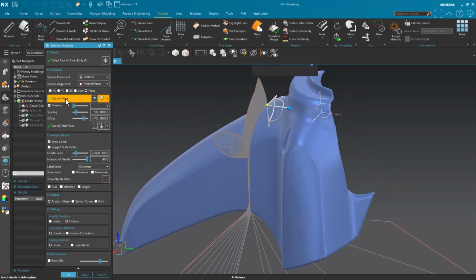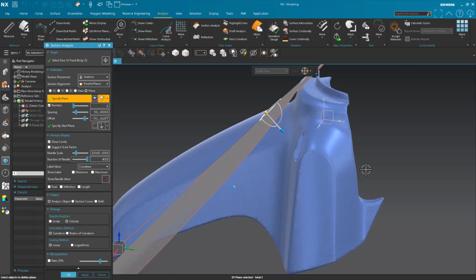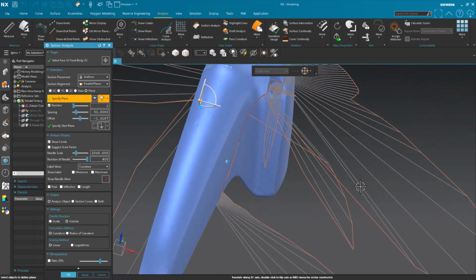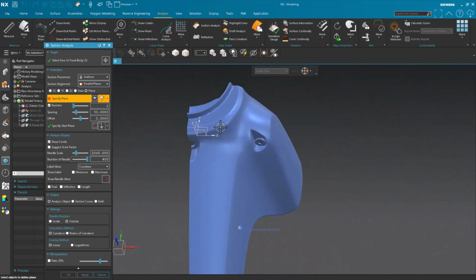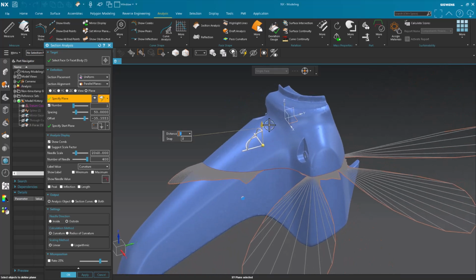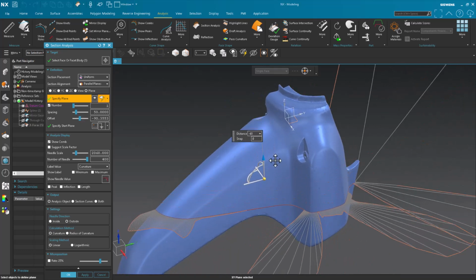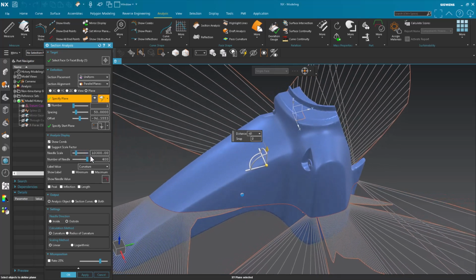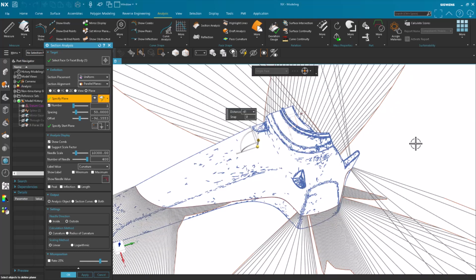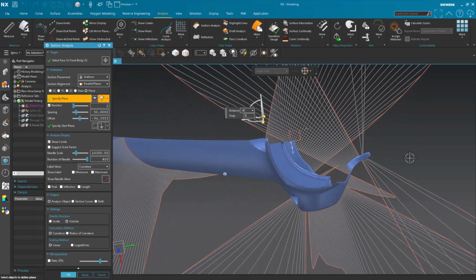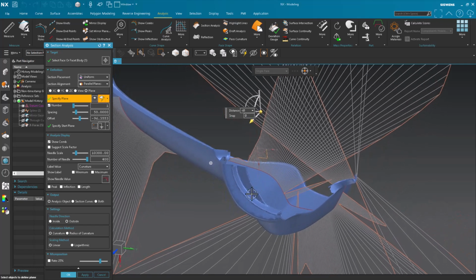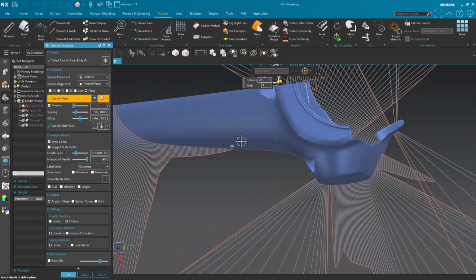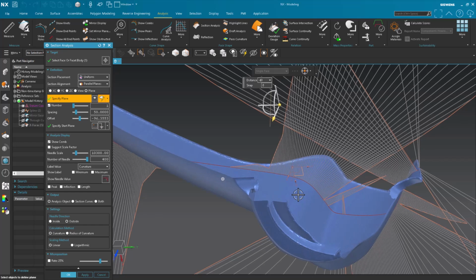Now, I'm going to orient this one more time to this view. And let me cut that section. Now, as I cut that section, actually, let me just go with this view. It was a combination of the two planes is why I was getting that. Now, I want to go to this section. And once again, I'm going to increase my needle scale. And let's see. What I want you guys to look at is, see how the needles here dive in and go behind the part?